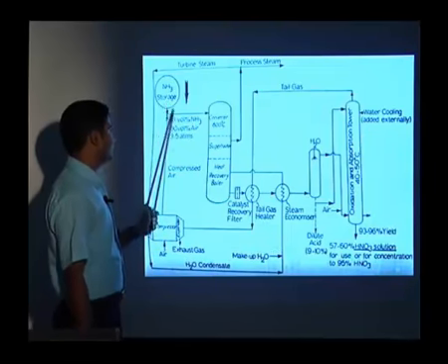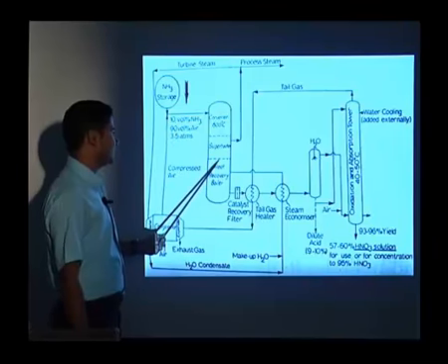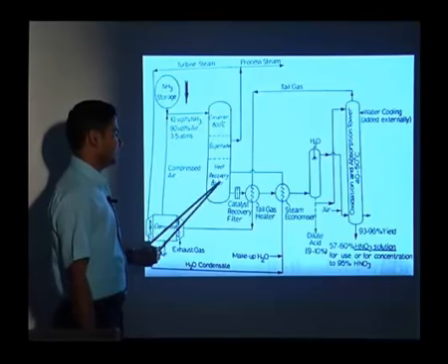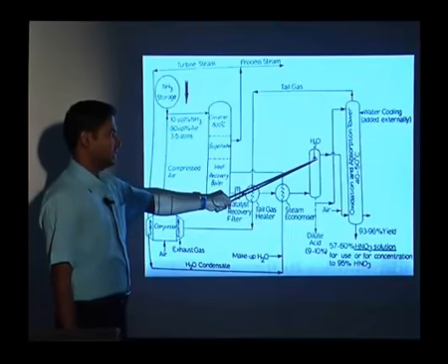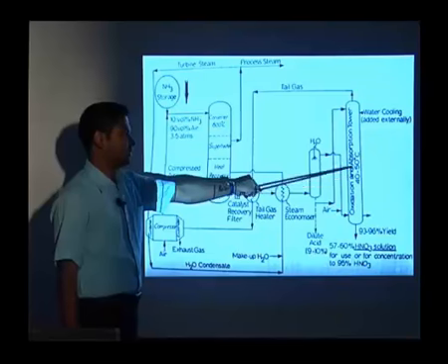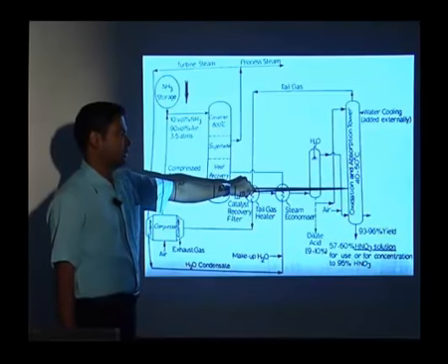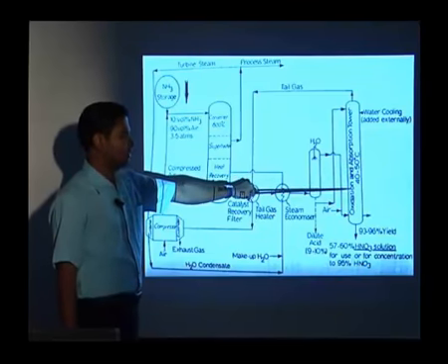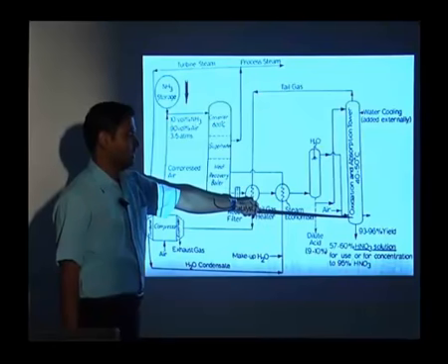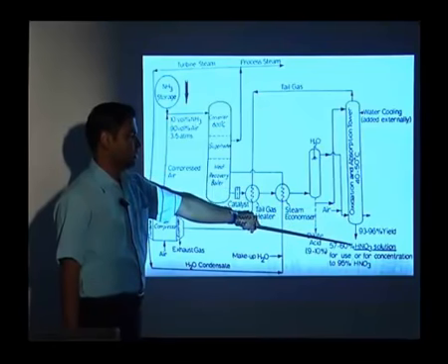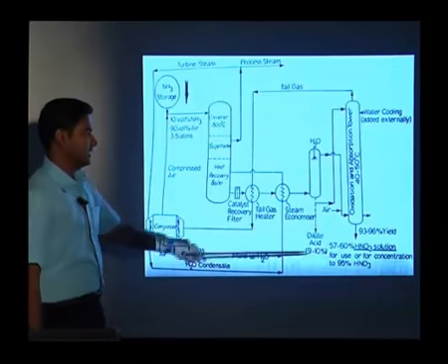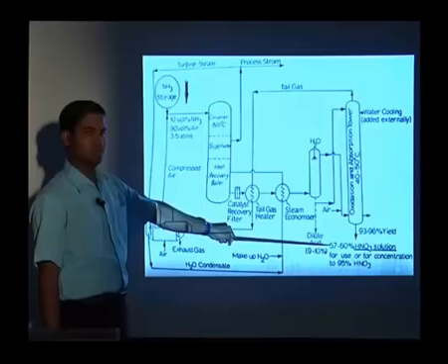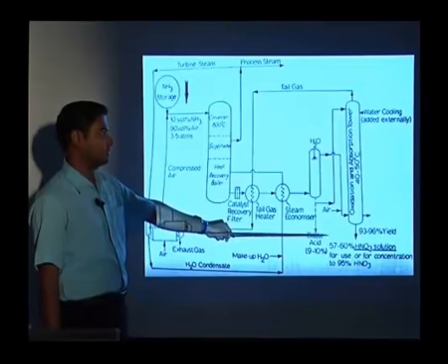So the main thing is the ammonia and air compressed at 3.5 atmospheres are sent to the reactor to form NO, and then it is cooled in stages, and then with water again to achieve the temperature of 40 to 50 degrees Celsius, where NO is oxidized to NO2, which we can react with water to get HNO3 as 50 to 60% nitric acid. That we can further concentrate with the use of sulfuric acid or MgNO3.